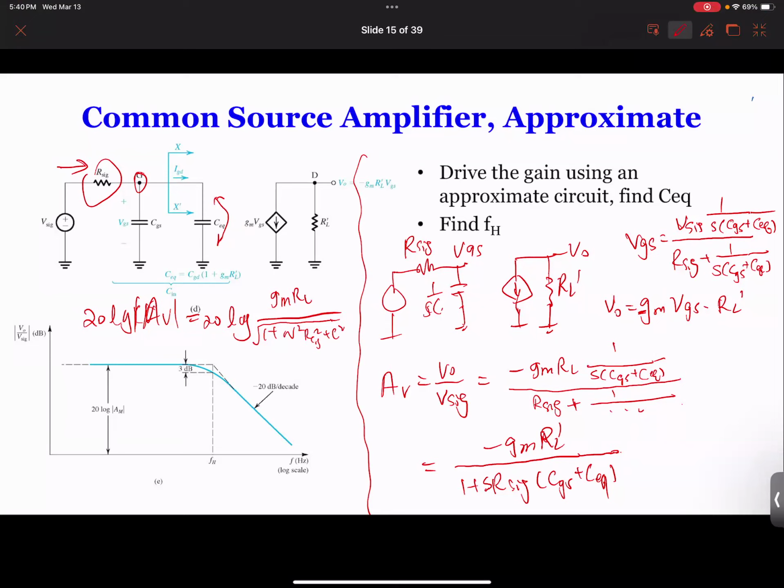So you can see, I want to ask you guys, if I plot this curve as a function of frequency in a logarithm, at what frequency do I get to this point, the green line in the middle here? What would this number be? Exactly, that's 1. Because when this is 1, 1 plus 1 is 2. And 20 log square root of 2 gives you minus 3. So this becomes 1 is what we need to look at.